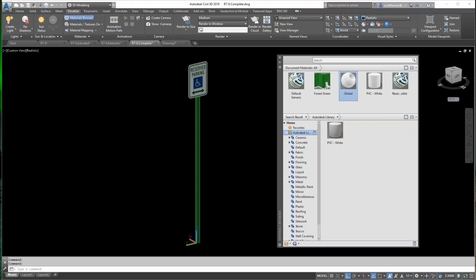Because of that, if you do a search on your web browser for Autodesk AutoCAD 2019 FBX 64, you will find that there is a zip file that will add an add-on to allow you to do that in 2019.